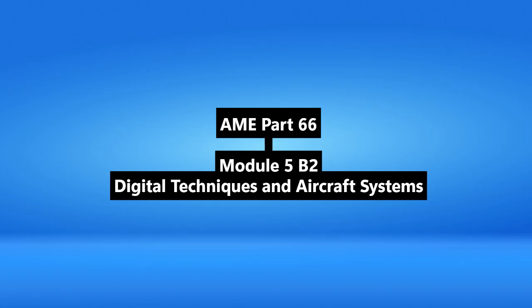Flash memory is very common now for storing things like operational flight programs, OFPs, in avionics boxes. These need to be persistent, but also updatable in the field. So if a system forgets its settings after you cycle power, you might suspect an issue with its non-volatile memory. Good tip. Okay, ROM for permanence, RAM for work, and all this stuff is built on integrated circuits, ICs.